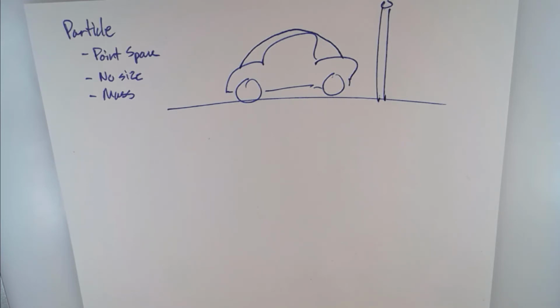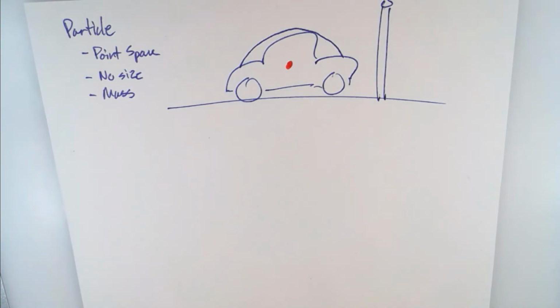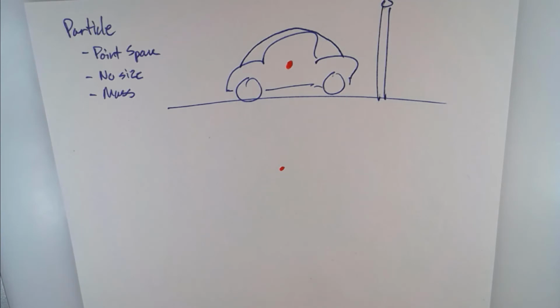So you're driving down the road, and we want to talk about the forces that are happening here. When we treat this as a particle, we say that all of the forces act at its center of mass, okay? And rather than having to be an amazing artist like I am, what we're going to do is draw free body diagrams. If I'm going to draw this as a free body diagram, I'm going to go like that, okay? You can draw a car if you want, but when we're dealing with a particle, a dot works, because size doesn't matter.